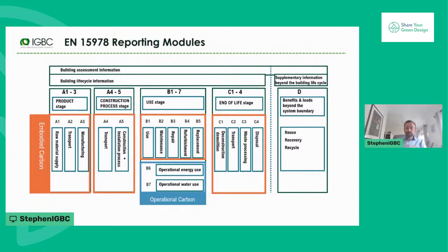We can get data on this from an EPC or an energy model if one's been created to give us an approximate annual kilowatt hour per year of demand. And from this, we can calculate the annual emissions from the grid. In theory, and most definitely in the past, this is the single largest contributor of emissions. But as it's spread out over 50 years in the methodology, the actual figure will depend on the carbon intensity of the energy grid during that useful period. And intensity will fluctuate, but should follow a downward trend in the future, we hope.